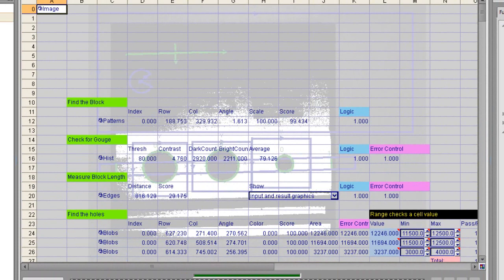So now if I go into live mode, though it's a little bit chunkier, it's reacting a little bit better. Basically, instead of trying to source up some of the information back in its buffers, every 200 milliseconds it's acquiring an image. So I'm getting a little bit better results than if I just left it on continuous running as fast as possible.